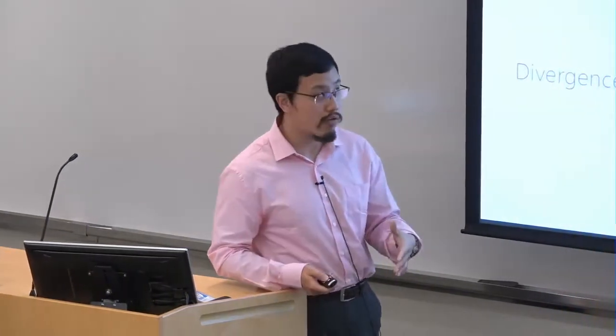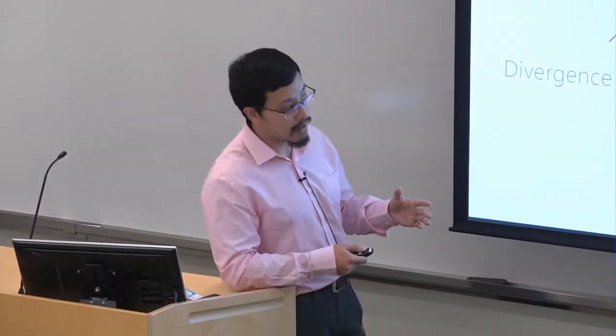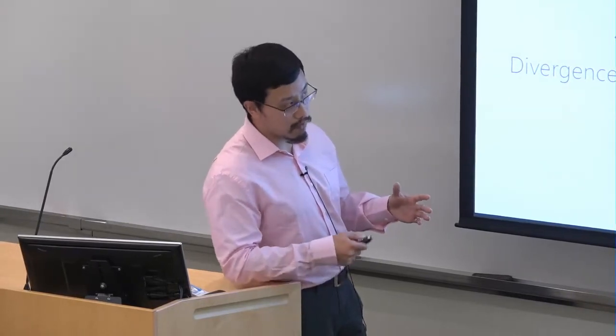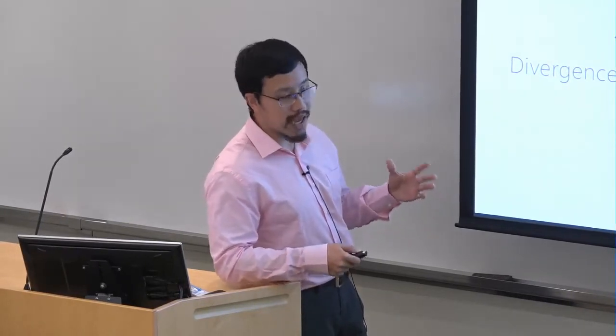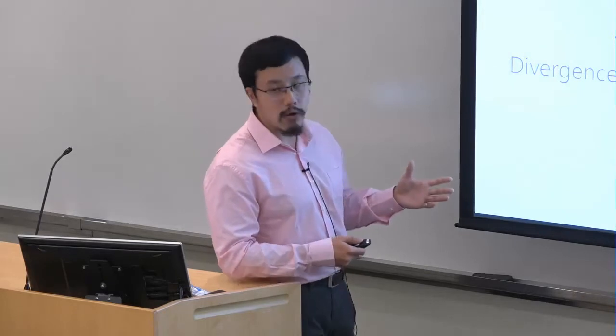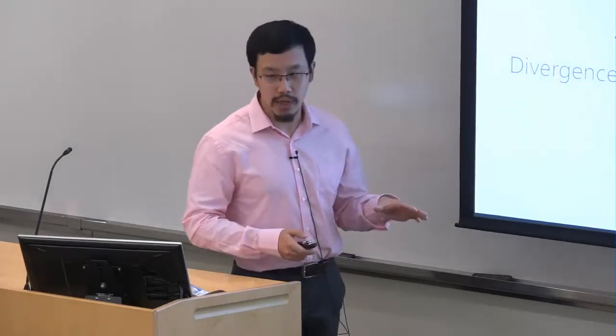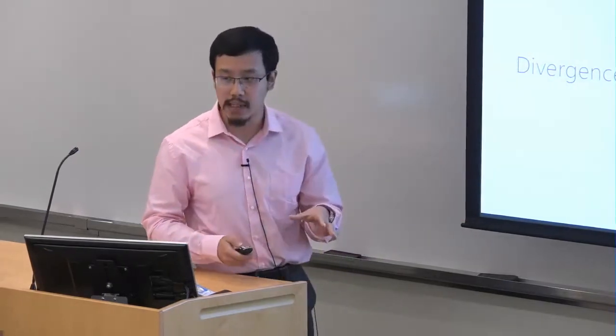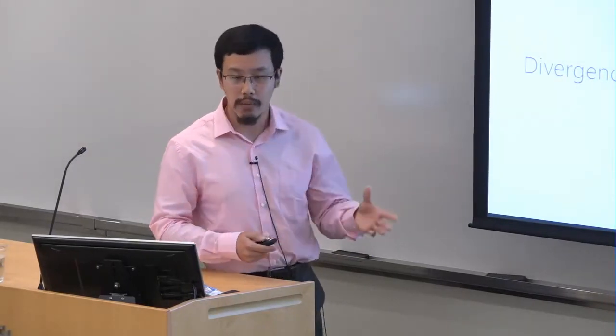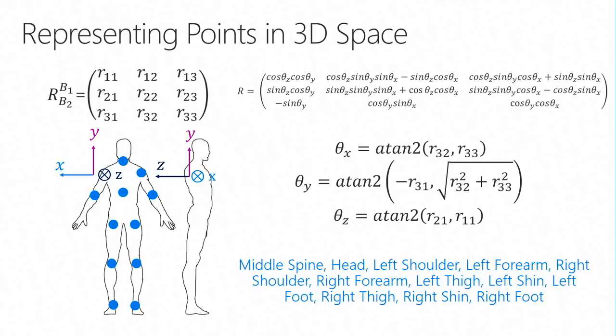And again, we integrate it over time t. We get the estimation. So also the magnetometer has magnetic interferences in indoor environment. We need to compensate that by this term. So this is the whole block diagram to get the sensor fusion. This is an existing algorithm by Madgwick, so it's a pretty robust and pretty precise sensor fusion algorithm for IMUs with little computational overhead.